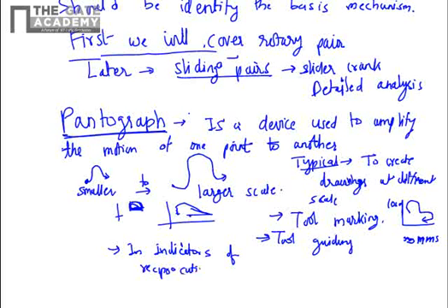So there, the motion of a pressure indicator on top of the engine, that is very small motion, is translated to larger scale, and it is plotted on the graph to get the crank cycle diagram, P theta diagram. So this is one of the applications.